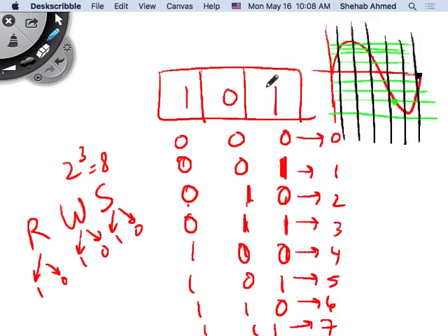Exactly. So I have to now. The computer is not going to see my complete signal all the time, right? The computer will see the signal at discrete values, because of its clock frequency, right? What else? It will also see the signal quantized at discrete levels, limited by the number of bits the computer is able to process.